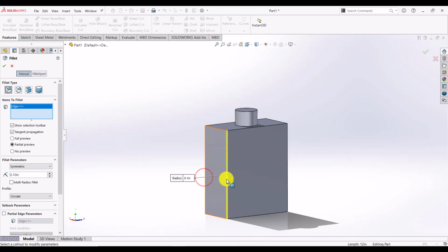You can see I didn't select that edge almost. Alright. One of the cool things about SolidWorks, it's a smart tool. So if I want to get that edge, the one on the back, I can just simply hover there and it's going to highlight. As you can see, I'm not rotating it around and selecting it.